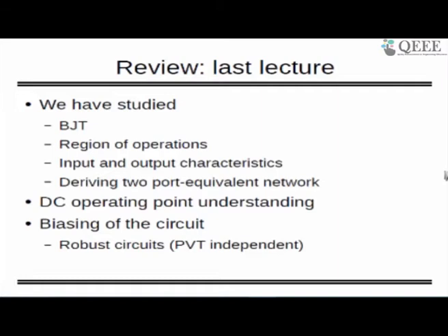So this is how we have to ensure that whatever we are making has to be PVT independent. For that we found some techniques, technique 1, 2 and 3, and at the end we found that the emitter degeneration technique is the base technique, which gives you the linear relation between input and output. Your collector current is better controlled through the input side, meaning the VBE side. So those things can be done, but this was for the biasing of the circuit.